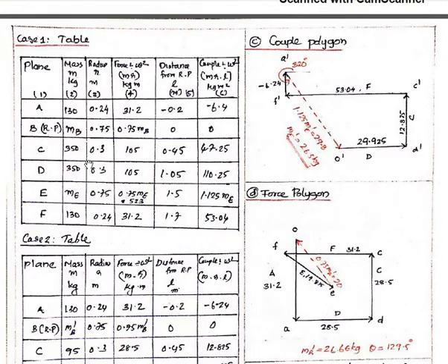So the table here will be 350 kilogram, and balancing masses MB and ME are unknown, and 130 kilogram for the coupling rod. Similarly, the radius for the coupling rod is 0.24 meter, the radius for the cylinder is 0.3 meter, and the balancing masses are placed at a radius of 0.75 meter.